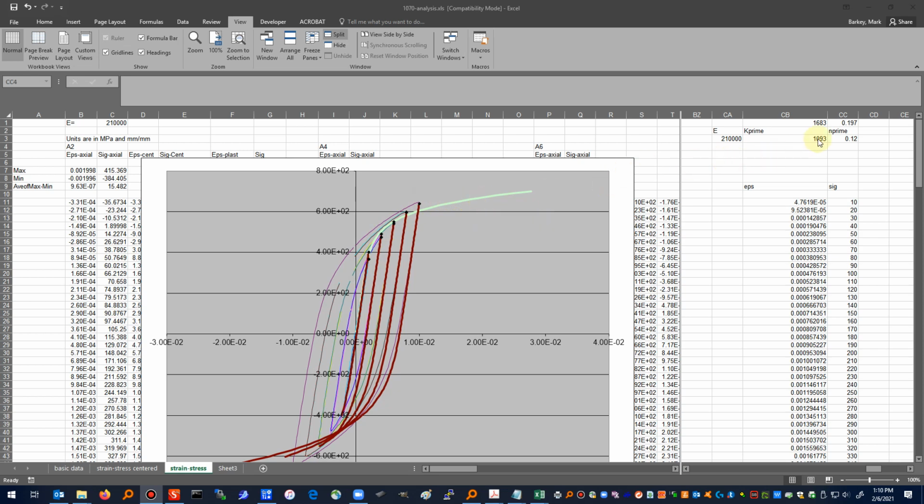So this was my first fit that I tried, the 1093 and the .120, where we included those two hysteresis loop tips. It fits this beginning part okay, but it doesn't do a very good job out here. If we have a significant amount of plasticity, we might want to fit this higher plasticity range a little bit better.